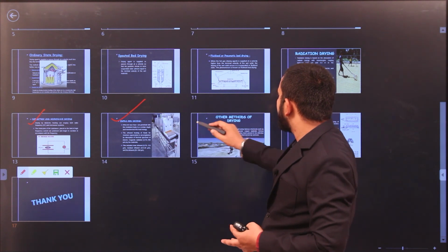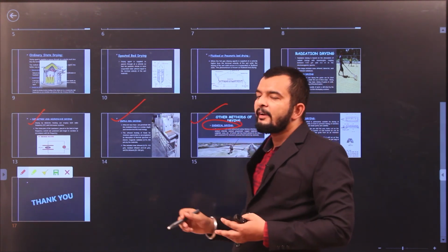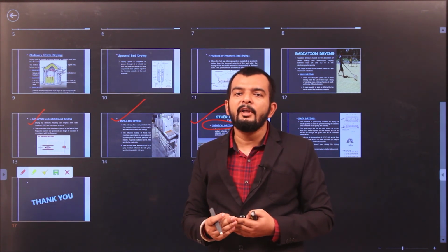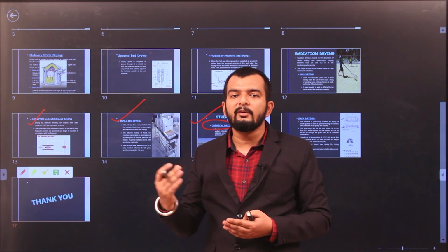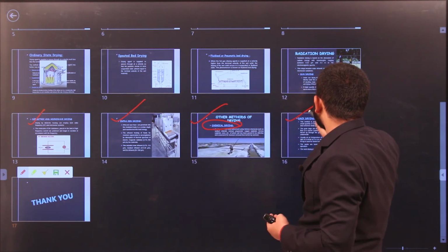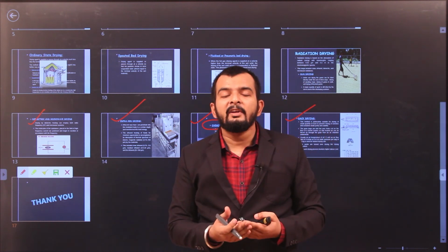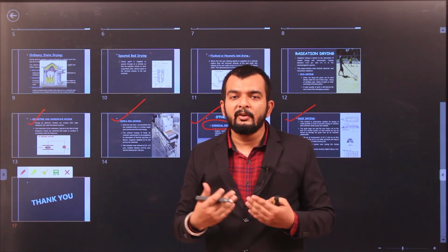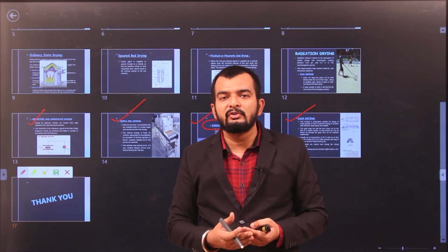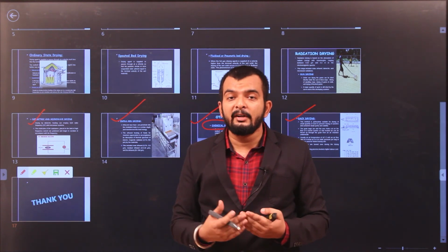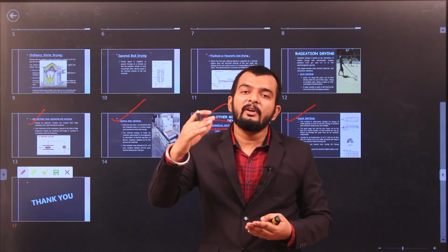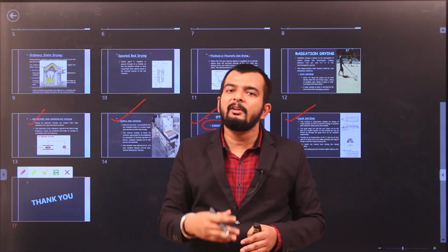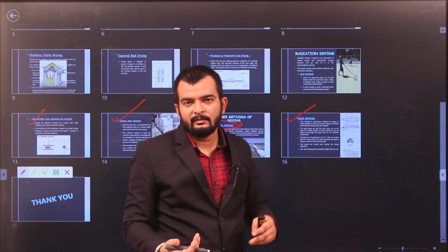Then under other methods of drying we studied chemical drying. Chemical drying means employing hygroscopic chemical substances or compounds to absorb moisture from the grains or your food material. Then we studied sack drying, that is when we have different varieties of seeds or grains and we do not have a sufficient quantity to process or dry them individually. So what we do is fill them in different sacks and pile them one over the other over a tunnel system where through holes hot air will rise through the sacks and lead to drying of the grains.